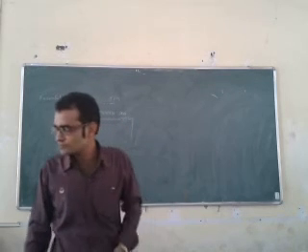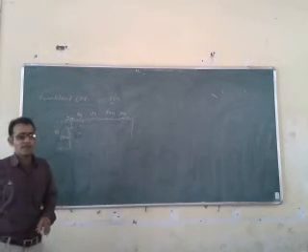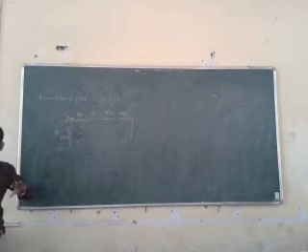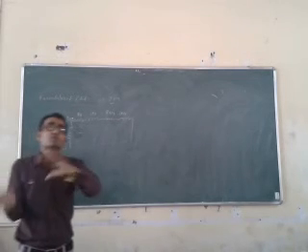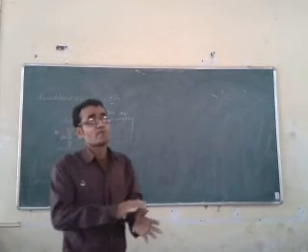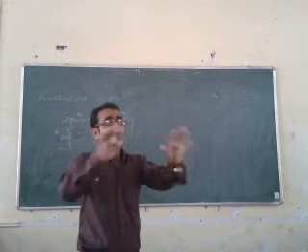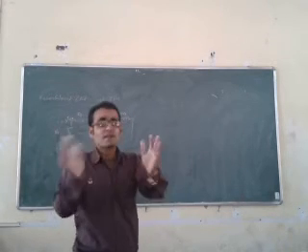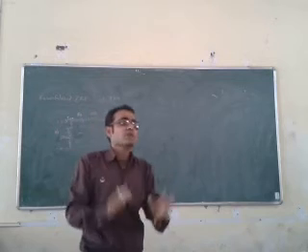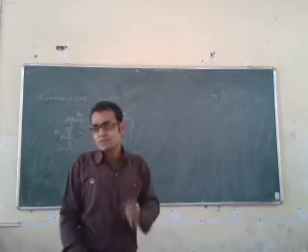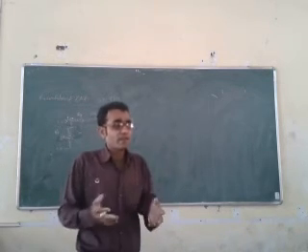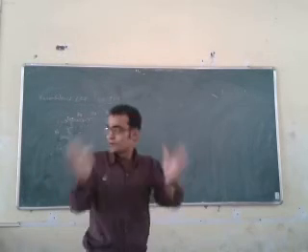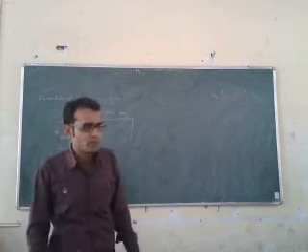Now let us move ahead. We are just understanding that there are two parts, one is the stator, another is the rotor. Whatever the parameters on the rotor side, we want to transfer them to the stator side. Why? Because we want to make the circuit very simple, or better, for further calculation and analysis. If the circuit is on one side and all parameters are on one side, we can easily calculate all the impedances and all the currents, and say this is the current passing through the rotor and this is the current in the stator.